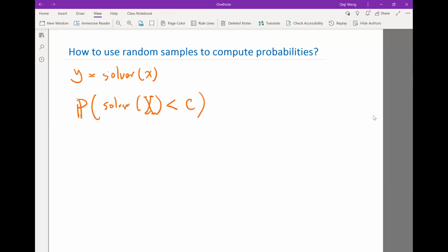And what you want to compute is the probability, for example, that the stress of the structure when it is in operation exceeds some maximum threshold, right? So you don't want that to happen. And you want the probability that it happens to be low enough so that you can characterize the structure to be safe. So this is when you have to compute such probabilities.